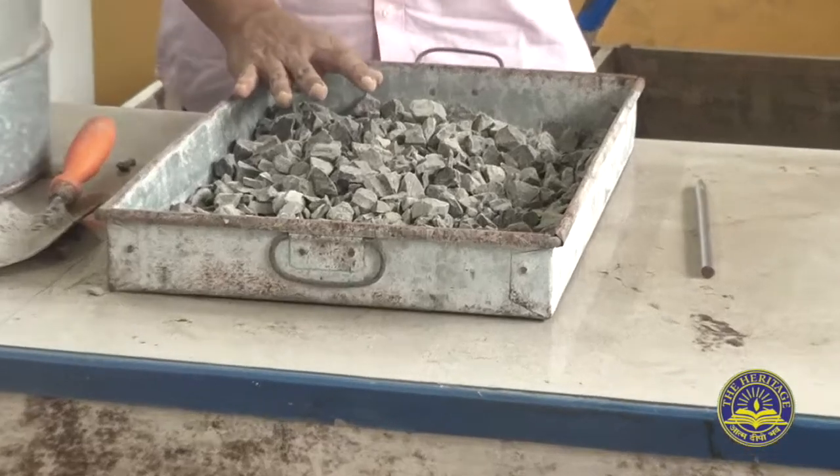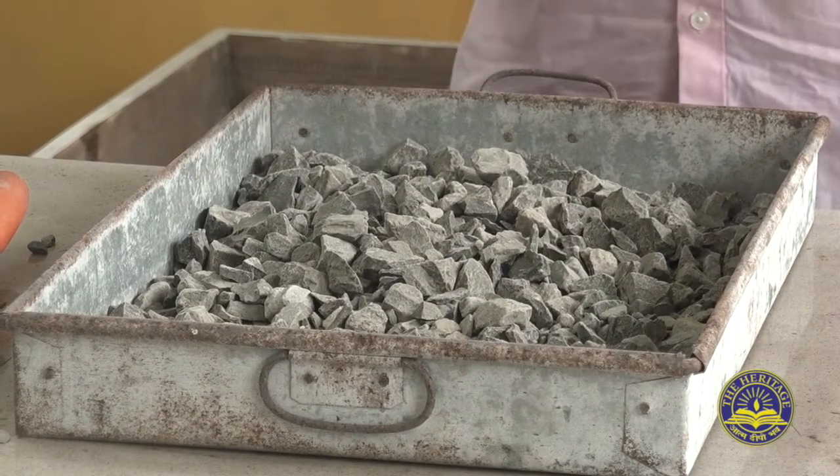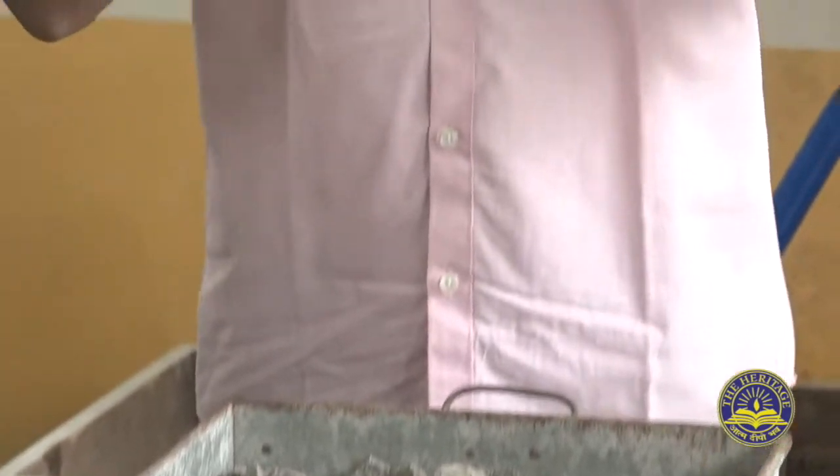So while the vehicle is in movement, this is your pavement and all your aggregates will be in this position, withstanding a huge amount of load. Now, what is the purpose of this experiment? Let's take, for example, that we have taken 5 kg of sample. We subject it to impact, and due to the impact, we estimate the loss in the material that is collected here.